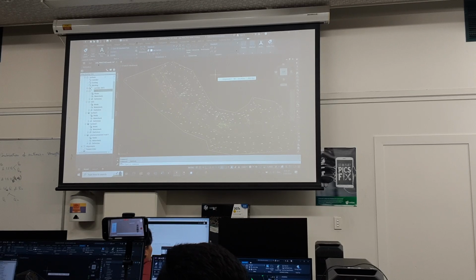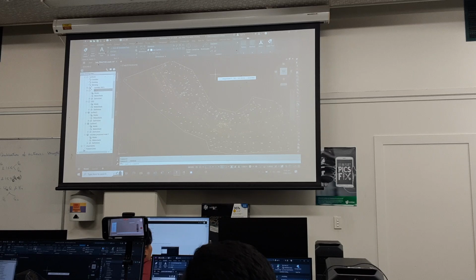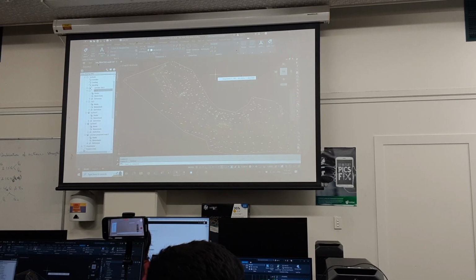Also, if there's a boundary or a house or a creek or a tree or a stream at a particular point that doesn't fall between the 20 metres, which is quite a long way, you might find that it's a couple of these classrooms in length, you should be picking it up on your cross sections.